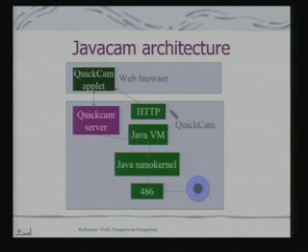So, effectively what you have is this camera, and you implement a quick cam server on top of your Java virtual machine. And at the web browser you can have an applet. So, you download that applet, it establishes a connection with the quick cam server, and you basically get the images downloaded and see what is happening from the standalone camera. Please keep in mind that this is not a webcam in the classical sense where you connect the webcam to a PC. This is a standalone Java camera. So, effectively the HTTP server is implemented on top of this simple 486.